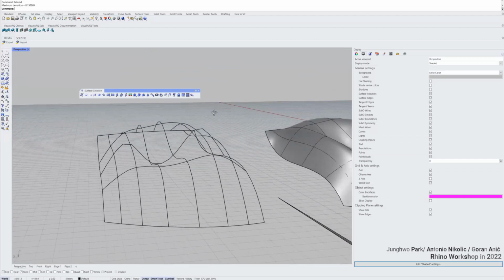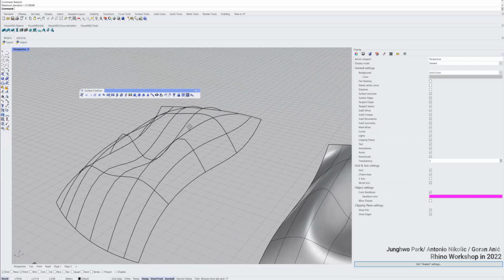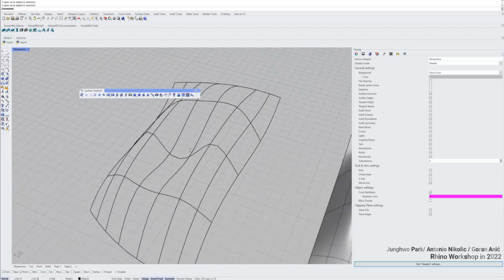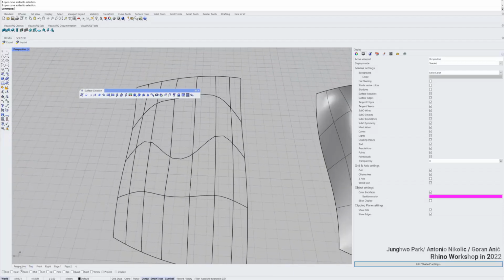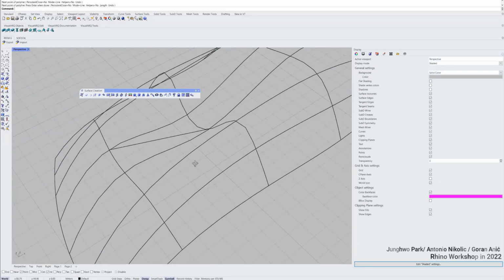Can you now make it create lines from intersection point to intersection point? Yeah. So you snap it here, intersect snap from your OSNAP, and you draw a line, and you can turn off endpoint snap, so intersection point, turn off smart, intersection to intersection. Okay. Amazing.